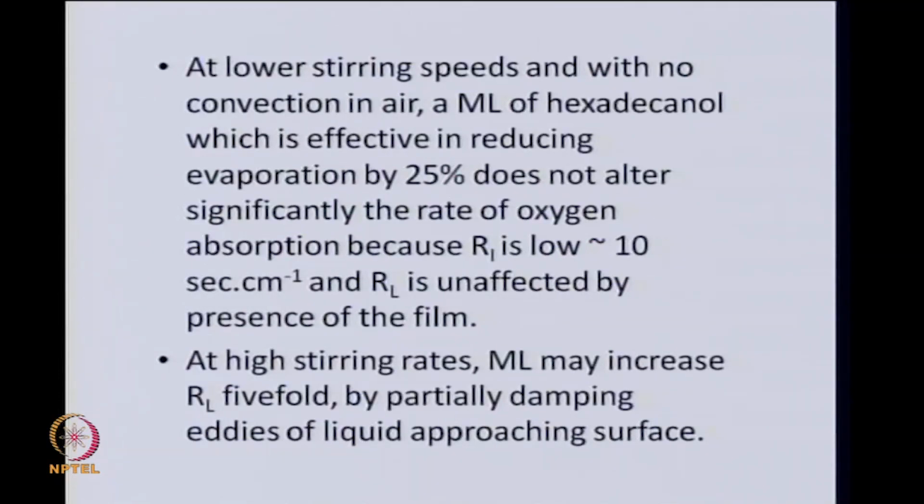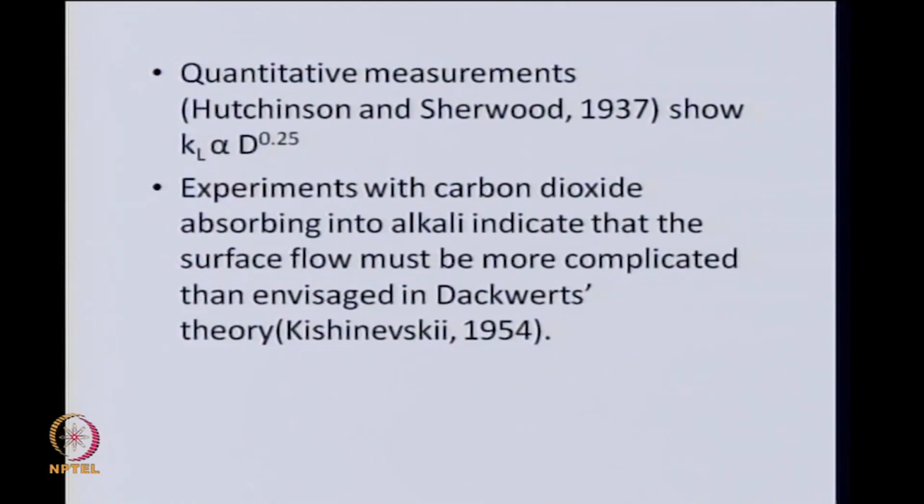At higher stirring rates, however, the monolayer can contribute a 5-fold increase of RL, partially by damping out the eddies, which are not now able to approach the surface as they would in the case of a pure liquid gas system.